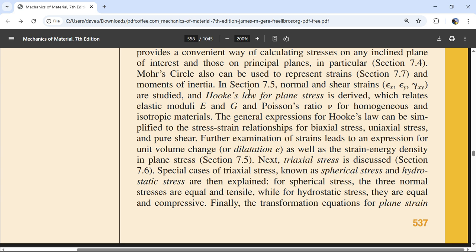All right, so these are just these ratios for those equations. And if we have no shear stress, we're going to have no angle change. In the tension direction, if I have no stress, no axial compression or tension, I'm going to get no change in length. So these are just lines that go through the origin, but their max values are a good way to actually get this constant.